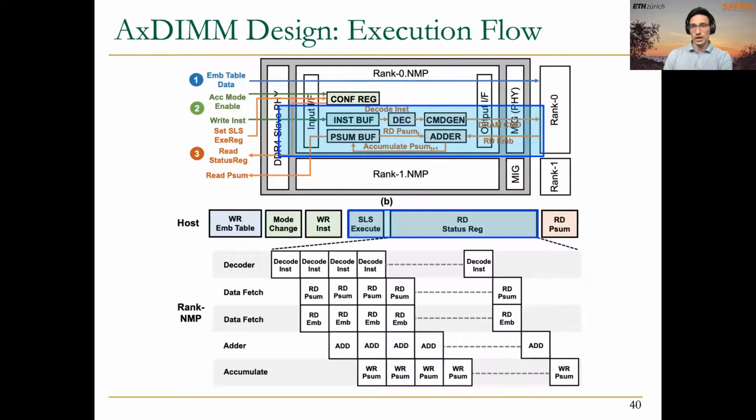Next, the host processor can launch the execution of the near memory processing kernel, the execution of the computation on the near memory side, on the near memory processing unit. To do so, it first needs to write the corresponding register in the configuration registers to start the execution, to signal the near memory processing units that they can start fetching instructions from the instruction buffer.